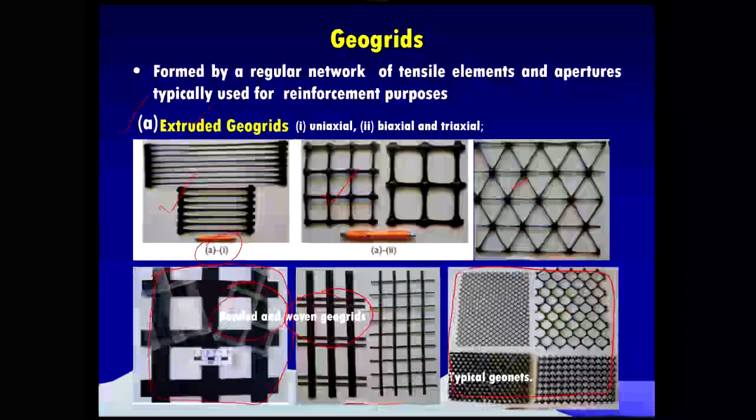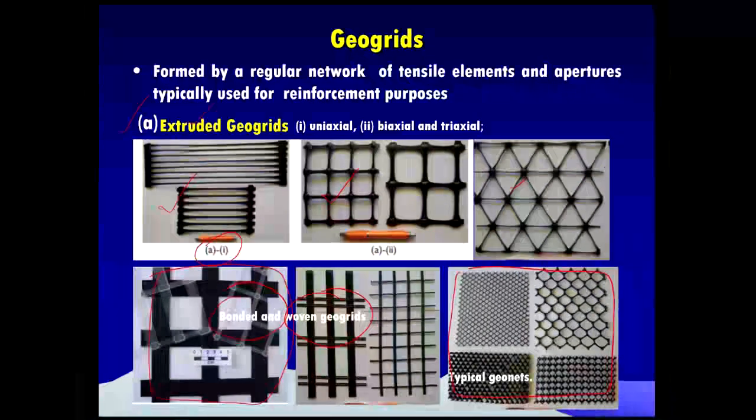One of the beauties of geogrid is that it consists of connected parallel sets of tensile ribs with apertures of sufficient size to allow strike-through of the surrounding soils, stones, or other geotechnical materials.